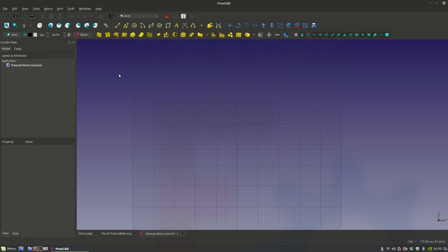So this is what the basic layout would look like for now. Alright, so now we seem to be ready to start laying out some stuff. One last detail to pay attention to all the time is the work plane. The work plane is essential to pay attention to, and also the snaps, because the snaps and the work planes are what allow you to feel comfortable working in any space mode and control the object.